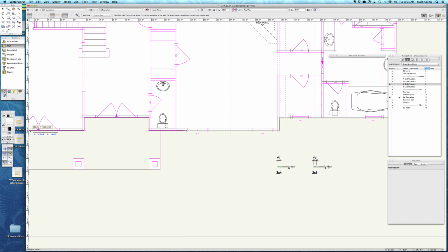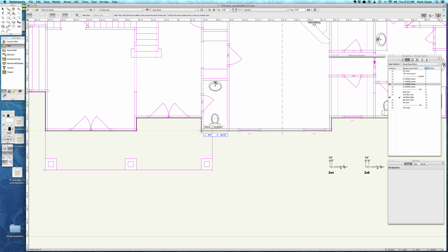The other way to know is a lot of these buildings are built. You can see that length L colon 20 foot 0 inches. A lot of these buildings are going to be built on 2 foot increments. So you got the sound cue, you got your shift key down so that you're drawing everything at perpendicular angles one to another. You have the visual cue, and then you also have that line length to tell you if you're drawing it correctly. So I'm going to click there, go up, that's to 2 feet, click, over to 10 feet, down 2 feet, over to 14, up to 6.